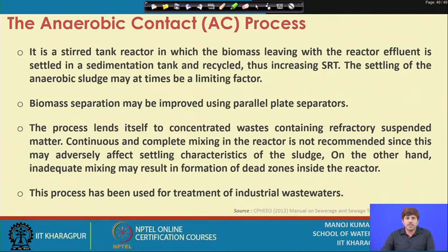The settling of the anaerobic sludge may at times be a limiting factor in this case. Since the growth rate is slower as opposed to the aerobic system, many times we see that the settlement is not as good as the typical secondary settling in an activated sludge process, which we discussed last week.